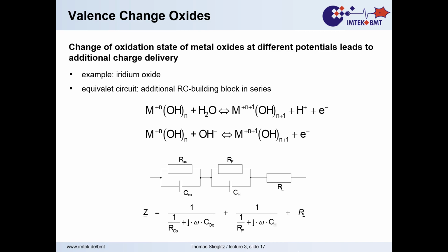If you do that modeling, you find that interface mechanism. So Helmholtz capacitance, faradic resistance is still valid, but you have in series to that an additional circuitry of those valence change processes, and then at the end again the electrolyte.